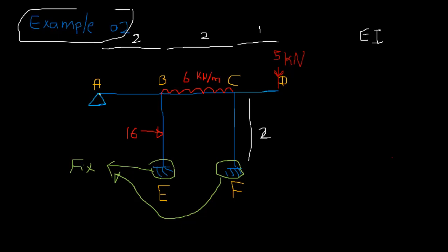On the other hand, you only have one bending moment of this member at this joint, so the final bending moment is going to be 0 anyway. That's why it is discontinuous. These two have 3 members connected together, so the summation of bending moment is 0. That means a continuous end.